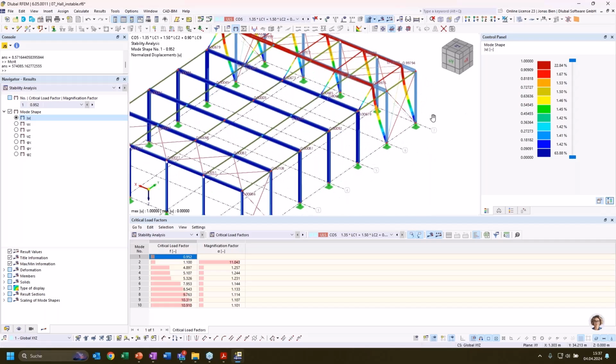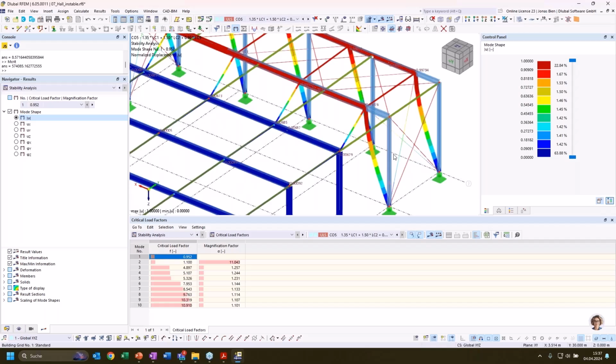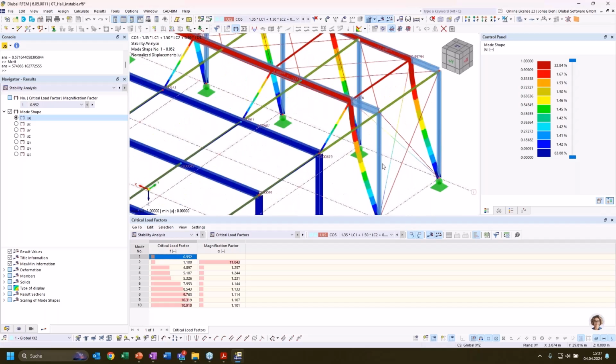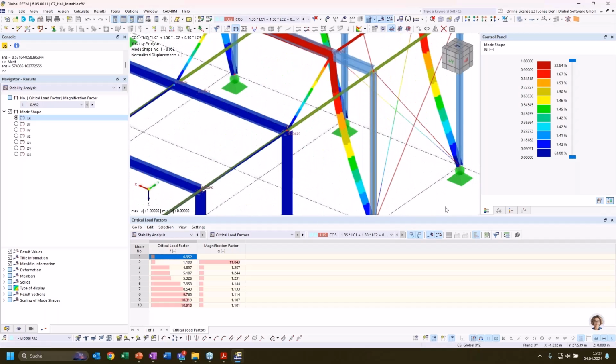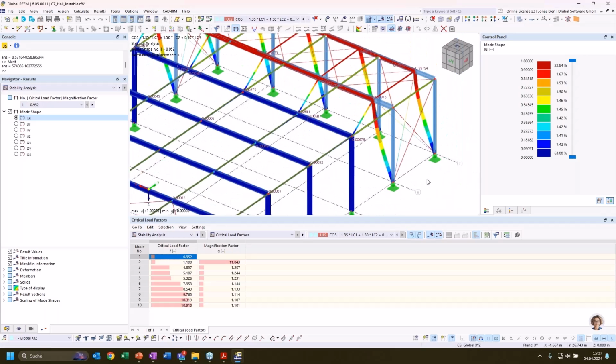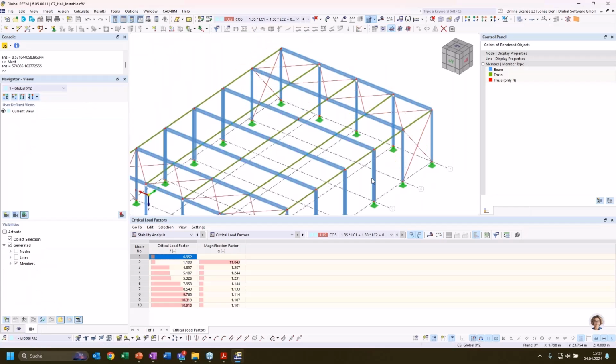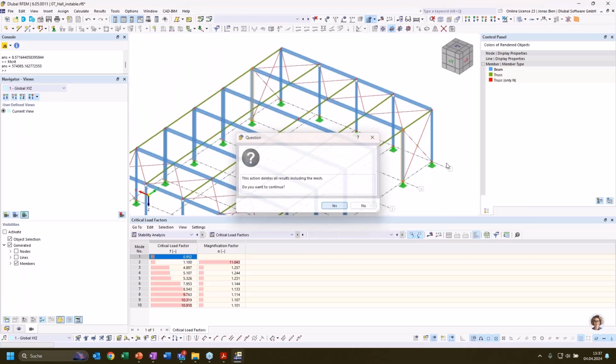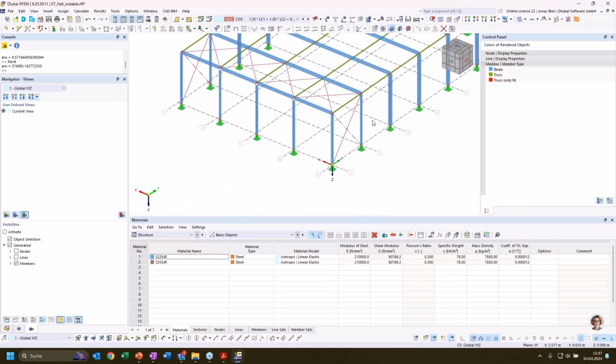And if I now look closely, I see that in my second frame, I set the wrong columns. I set the columns from the end frames, which are much too weak for these internal frames. But this can also be quickly resolved by just copying and overwriting the member dimensions with the columns from frame number 3 or 5.